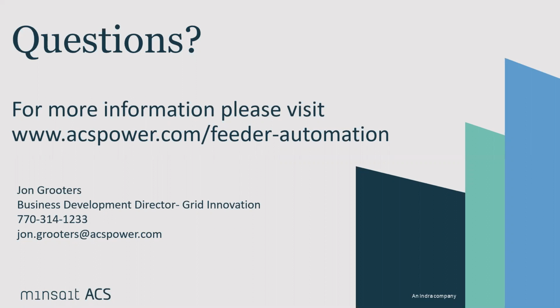Yeah, that's a good question. Fortunately with this system, it's a pretty simple process because it's template based and we're not having to import the source from a geospatial model. The templates, as John showed during the example, are built with typically more circuits than you would probably deploy on a particular island, and then overpopulated with devices, more devices than you typically would see on a distribution circuit. So you have flexibility when you're defining the islands and the circuits to choose where those devices are and which ones you actually want to include in the model and which ones you don't.